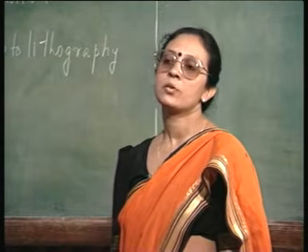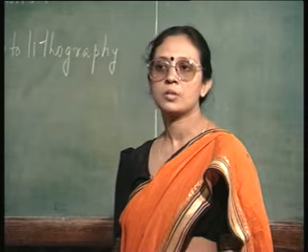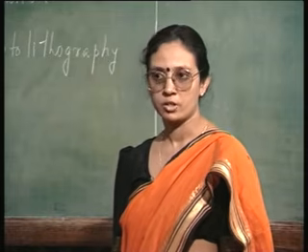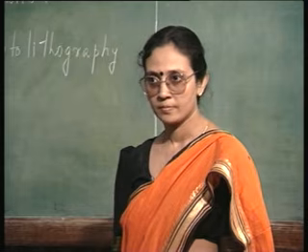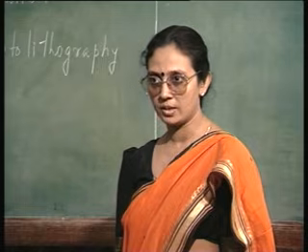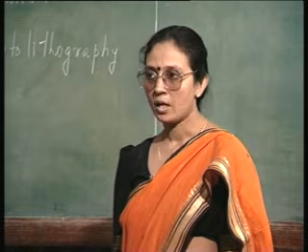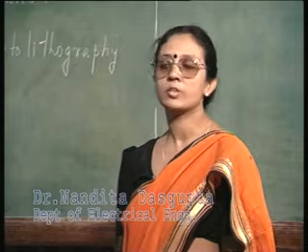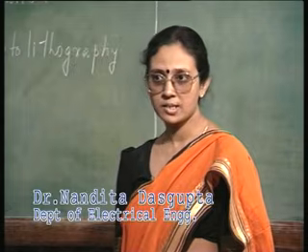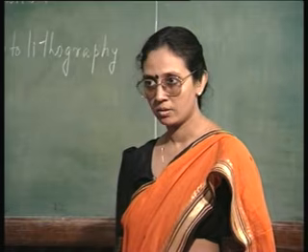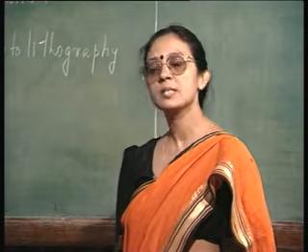And then you subject it to a particular radiation, most commonly UV radiation. As I told you, the photoresist is a light sensitive material. So, through the transparent regions of the mask, this photoresist is exposed to the UV light radiation, and then its properties change.